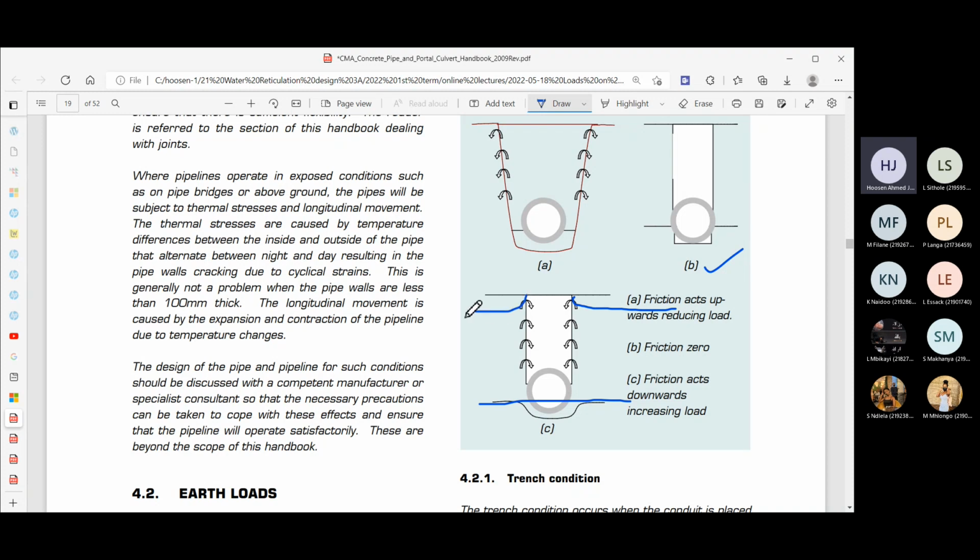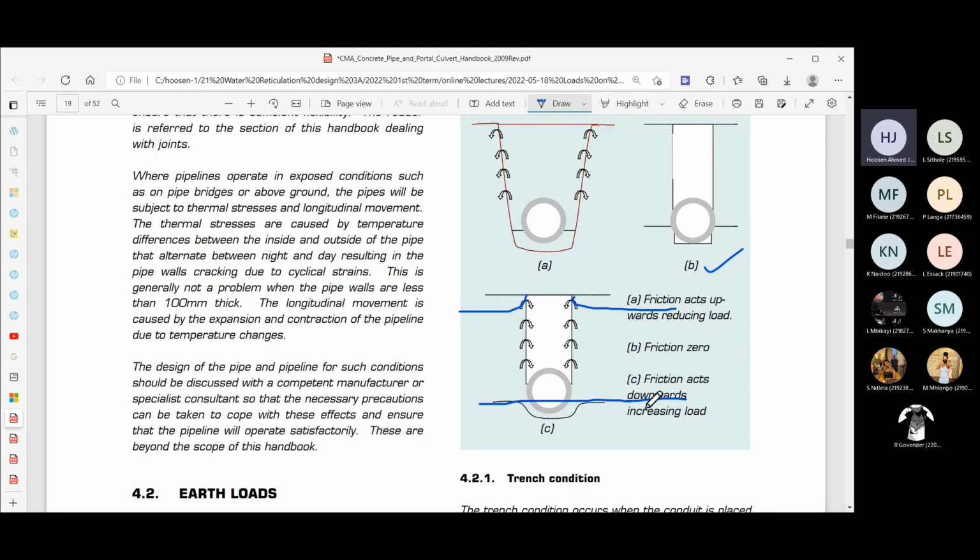So you get rain or whatever like that, and the soil particles will get lubricated, and you can then get settlement of this pipe, or even vehicular traffic, or just under normal circumstances in time, this will settle down like that. Right? For example, when the municipality digs up a trench on the road, when they do repairs, and then they backfill it, and then you see that it settles. So even these guys who come and lay the fiber cables, they dig a trench, and in time, where they've dug, you actually see that settlement taking place there. So you'll get settlement over here along adjacent there.